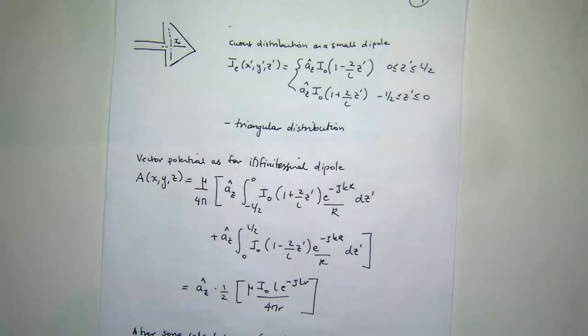Well, the reason why we studied it was because there were two reasons. First is if we want to listen to an AM radio station, or for whatever reason we're constrained and we have to produce a very small dipole relative to the wavelength of the signal that we're trying to transmit. We showed that, for example, if we had an AM radio station which is transmitting at 1 megahertz, it has a 300 meter wavelength.